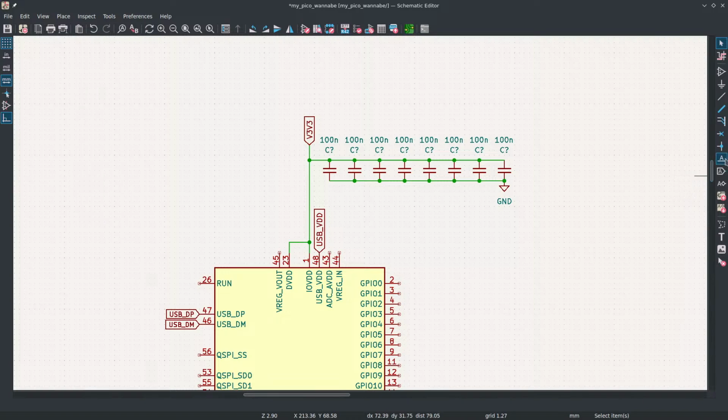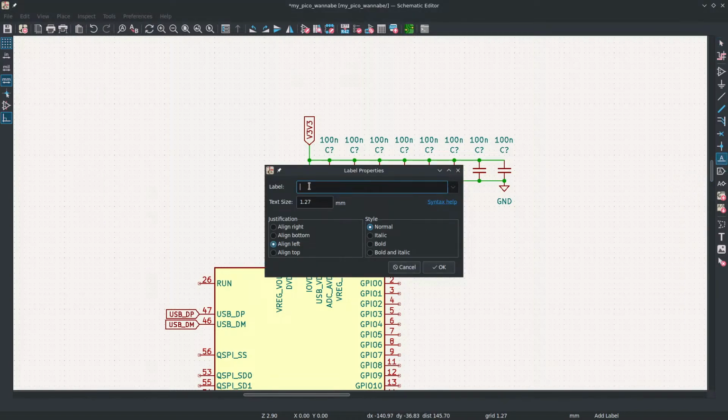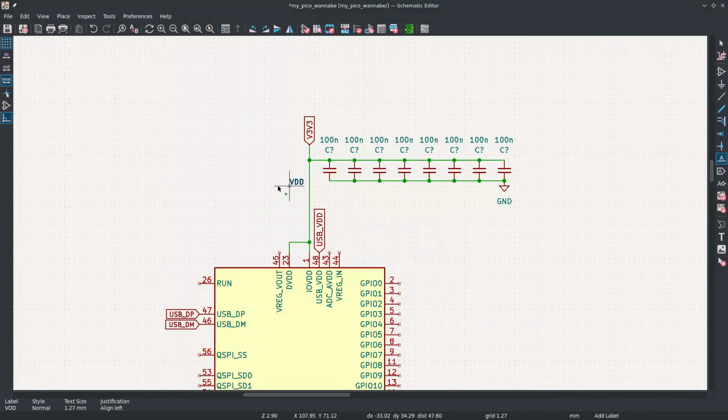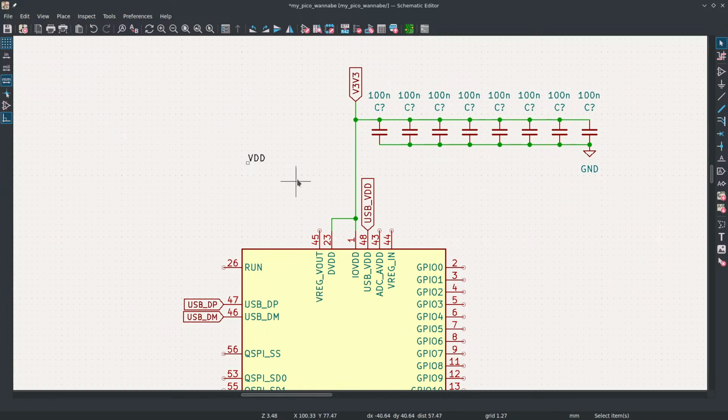Okay. The net labels, part of the reason I don't use them is they don't have like a flag around them. I will use them, but I'm not going to use them for the sort of air wires because they're not very visible, and that's more of a stylistic thing. Also when you go to route the circuit board, if you use all global labels, then you don't have any nets that have the same name accidentally, and you have to try and understand which is which later. Right.